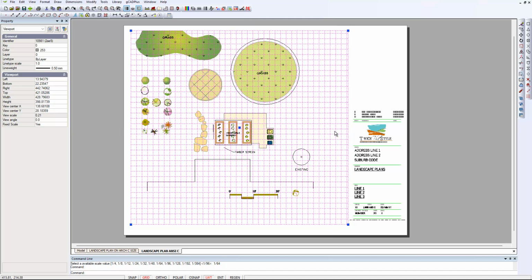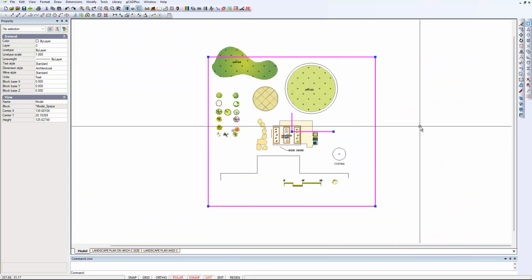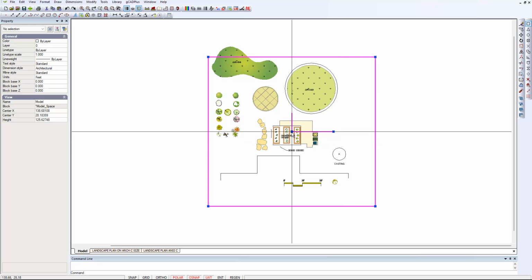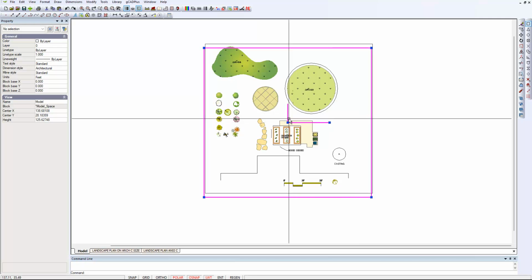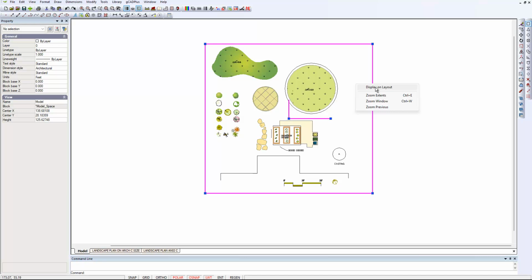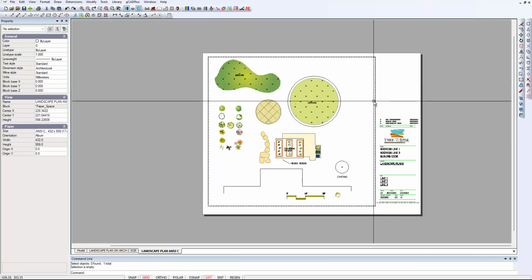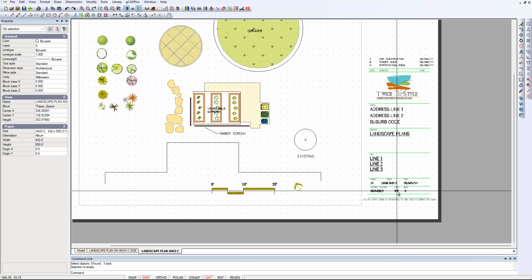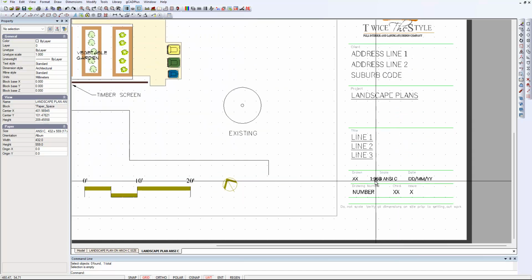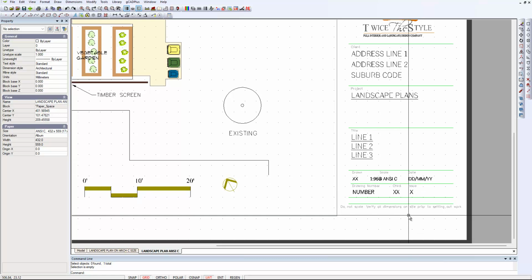And if I click in the area there, we move to a magenta box. So this is, in a sense, the porthole, and I can move that view like so, and maybe a little more, and then display it on the layout. To get rid of that dotted border, just double click inside. So we could now print that design, and we could change the value there from 1 to 96 to 1 to 64. But I digress.